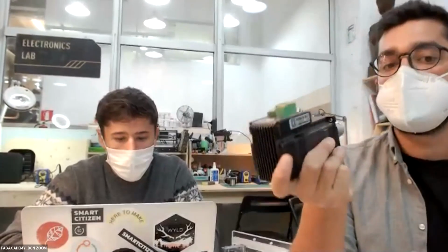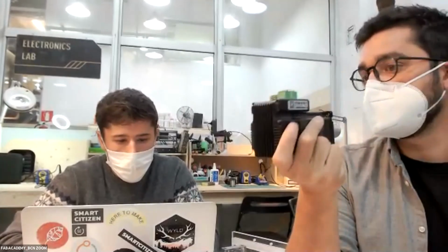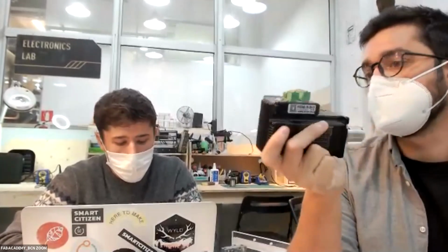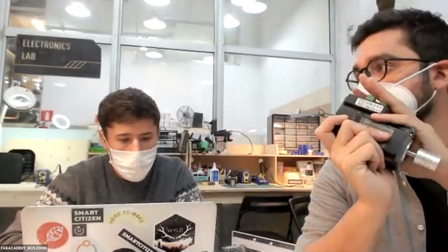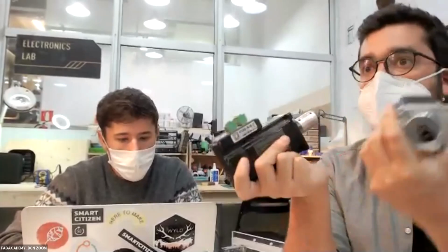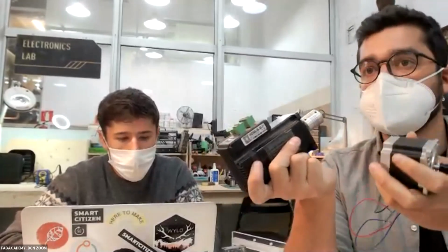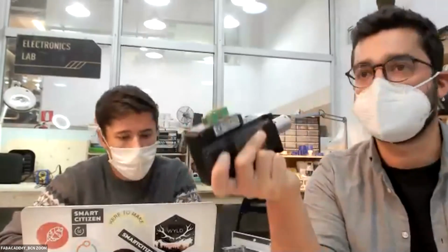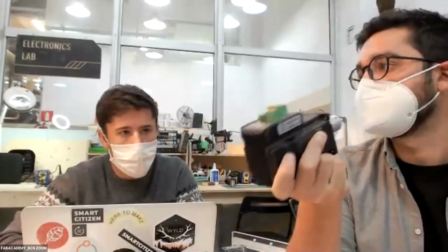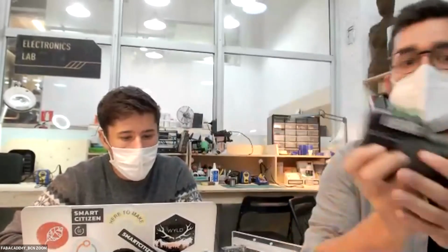What happens? This is a slightly more complex piece of hardware, and in general it's always better. But the control is more difficult, and especially it's way more expensive. A stepper motor, a NEMA 23, costs, I don't know, like 20 to 160 euros. The servo motor is 300 euros, and this is the cheapest one you can find. It's a super Chinese copy of another. This servo motor is not completely a full servo motor. Servo motors right now start from 1,000 and up.